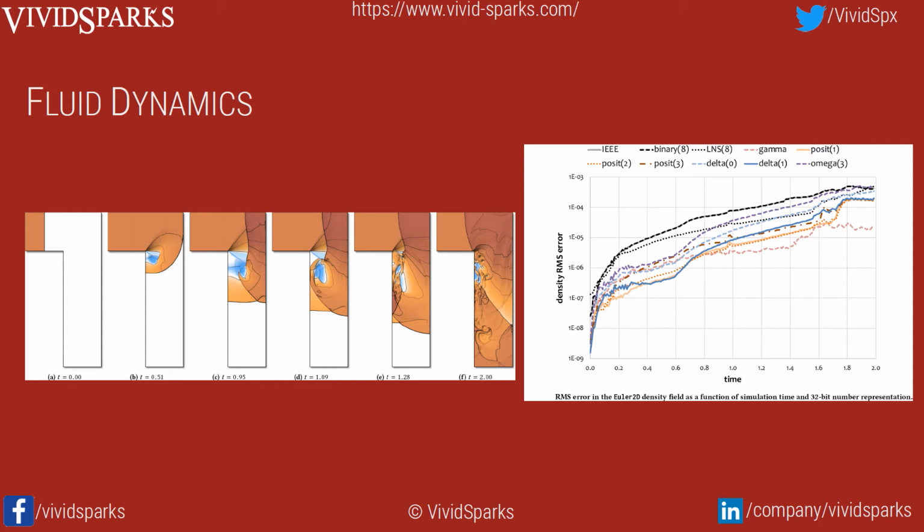Then the reflected shock wave breaks up the vortices shedding off the corner and reflects again off the near wall several times. Eventually the flow moves down the channel with a propagating sequence of oblique shock waves and a great deal of wave interactions.